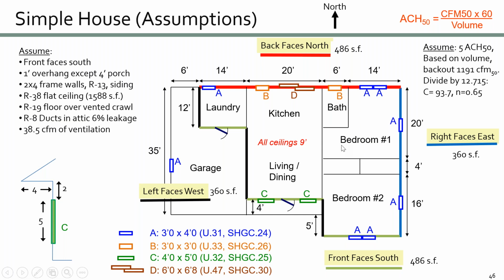We did this, Joey, back in our other webinars. We talked about this. This is about a 1,600 square foot house. So I'm going to add 16 CFM plus people times 7.5. This is a 2-bedroom house, so we're going to assume 3 people. 3 times 7.5 is, I think, 22.5. Add that to the 16. That's how I got that number.